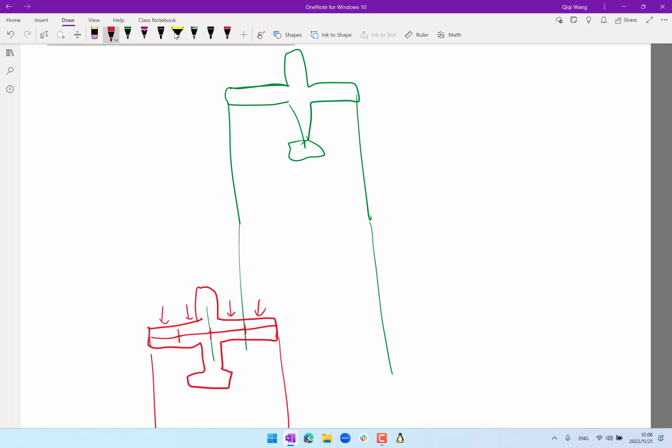Okay, the second question I got, also very good, is about the batteries, right? Where we have a Pareto front, and where do we look at on the front? What is the combination of specific energy and specific power? So my suggestion, at least for the first week, is actually very easy, because if we can compute the total drag, then if we multiply the drag with the speed, we know how much power is required to counteract the drag. And if you divide that power by how much weight of battery you can squeeze into a 737, you have the specific power.